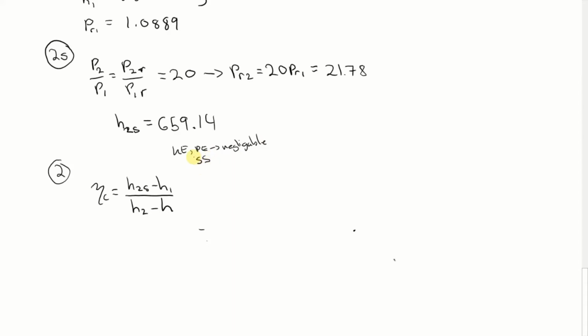So in this question, we're told the volumetric flow rate, but we aren't told anything about the diameter of the inlet, so we're not going to be able to find velocity. There's no information about this. There's no information about changes in height, and there's this: we have to assume steady state for this type of question because the non-steady state version is significantly more complex and beyond the scope of this course. So to me, all of these check out, so we're happy to use this version of the equation.